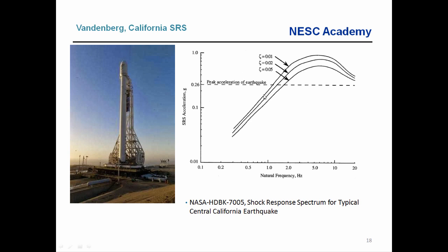Or we could just take that El Centro time history, which we have in ASCII text format and have already taken a look at, and use that to base drive our launch vehicle for a finite element modal transient analysis. That would be better because we'd be modeling the launch vehicle as a continuous system, at least as best we could with nodes and elements, and we could account for the fact that there are several modes that could be excited.